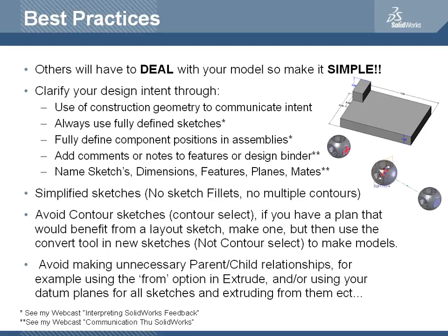You want to convert that layout sketch into different sketches, and I'll go ahead and show an example of that. Another thing to keep in mind while all this other stuff is you want to avoid making unnecessary parent-child relationships. When you make parent-child relationships that you didn't intend for, when you delete a feature out, you're going to take out all of its children.